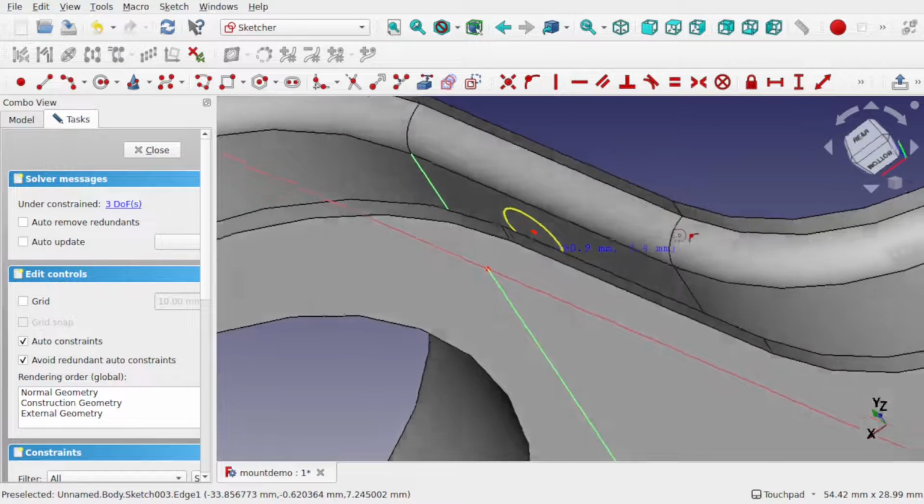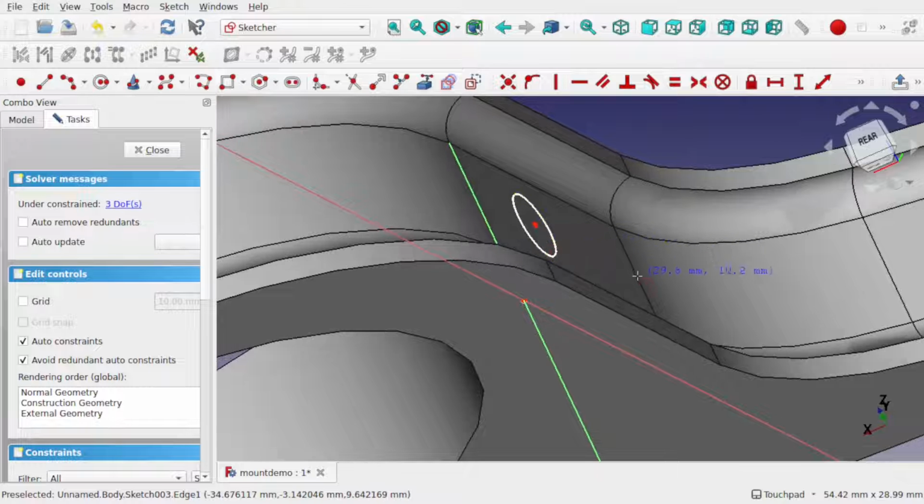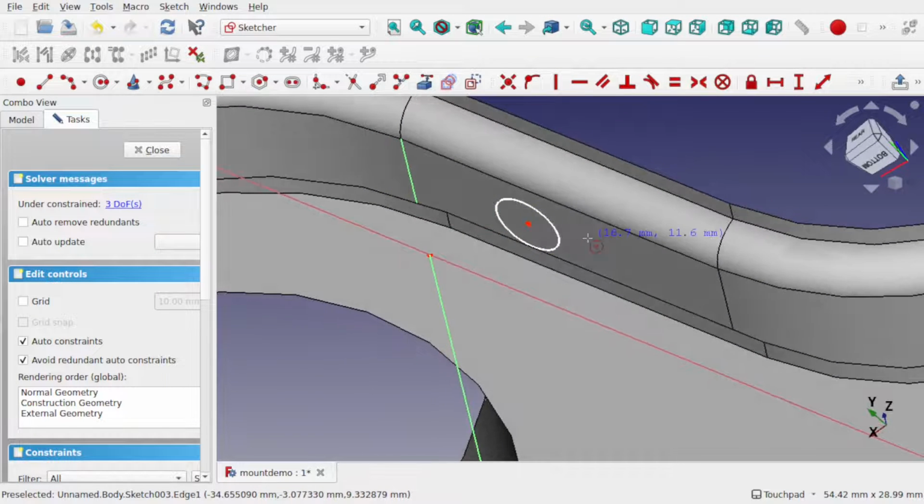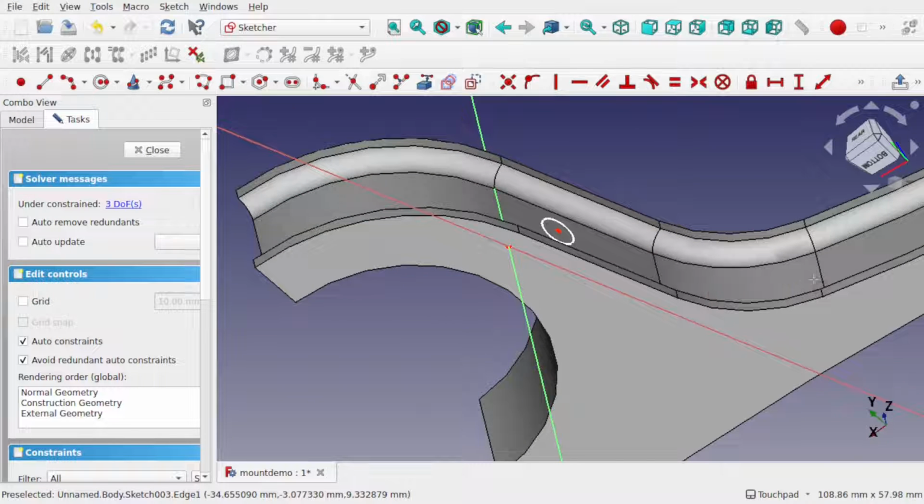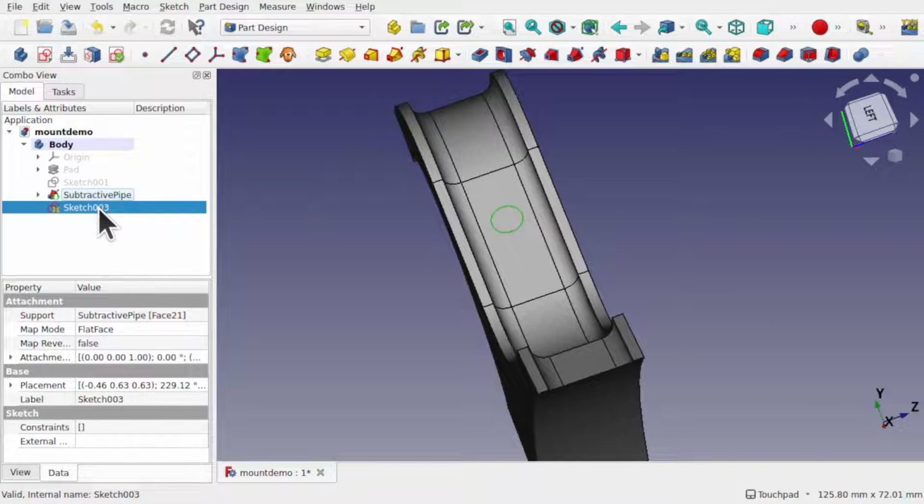And this is what we're looking for, because if you look at the angle, it follows the angle of that face. So we need to follow the angle of these faces here, and there's a little trick of how to do that without using such things as datum planes or the curves workbench, but with sketch placement. So let's close that and delete that sketch.